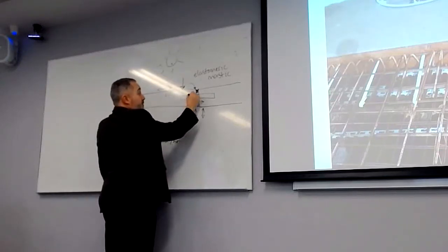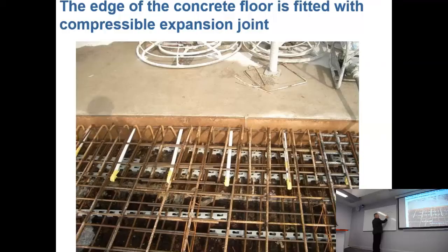So this bar is stuck in the concrete. So as you're finishing off your concrete, you put in these white bars. Then you can paint a layer onto this reinforcement, and maybe have a little cap on the end, which is this yellow here, so that when this concrete is moving backwards and forwards, it's not connected to the steel, and therefore it can move freely.